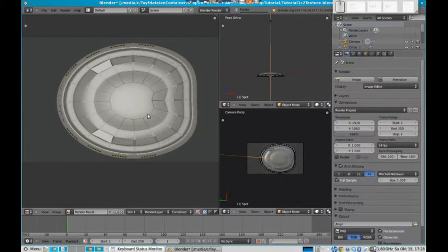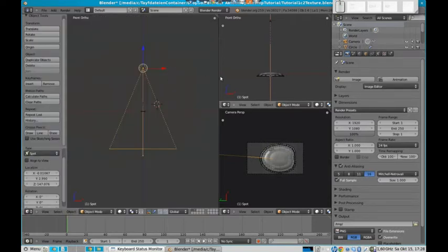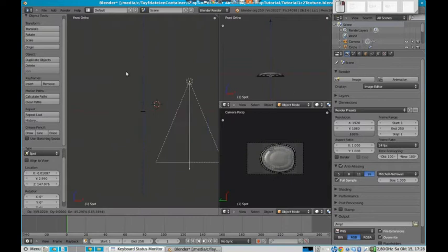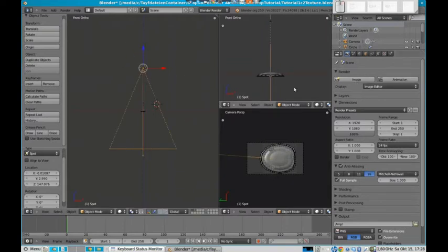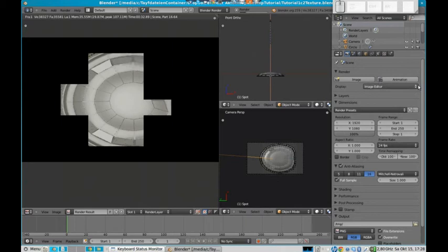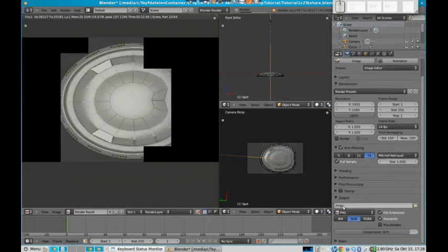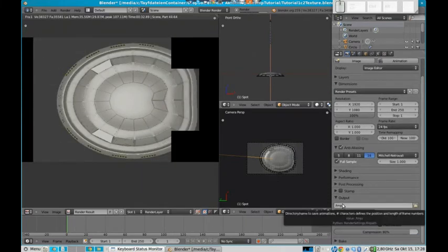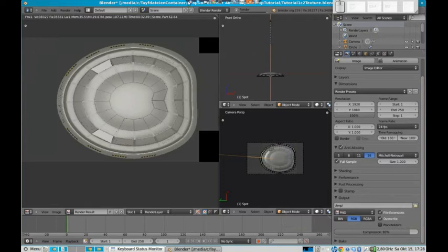Another point of Blender which I should tell you is cancelling this. If you press the F12 key, you will get a rendering here, full rendering, but the file will not be saved. So just press animation, then the file will be saved in the location which is given here. So let's wait again until it's ready.